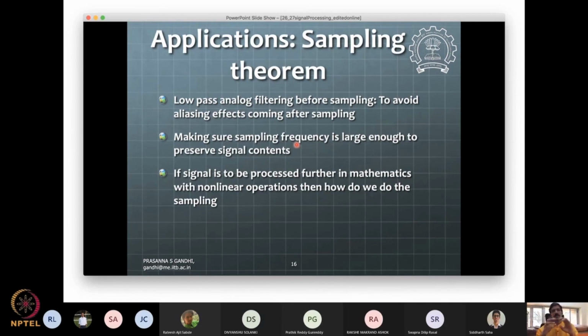These RC filters are first order filters. They'll have a slope, and that slope will allow some frequencies higher than the cutoff also to pass through. If you know 1 over tau s plus 1 is the transfer function for a first order system, then its Bode plot is simply obtained by using this tau. 1 over tau is your cutoff frequency, and beyond the cutoff frequency you will have a 20 dB slope roll-off.